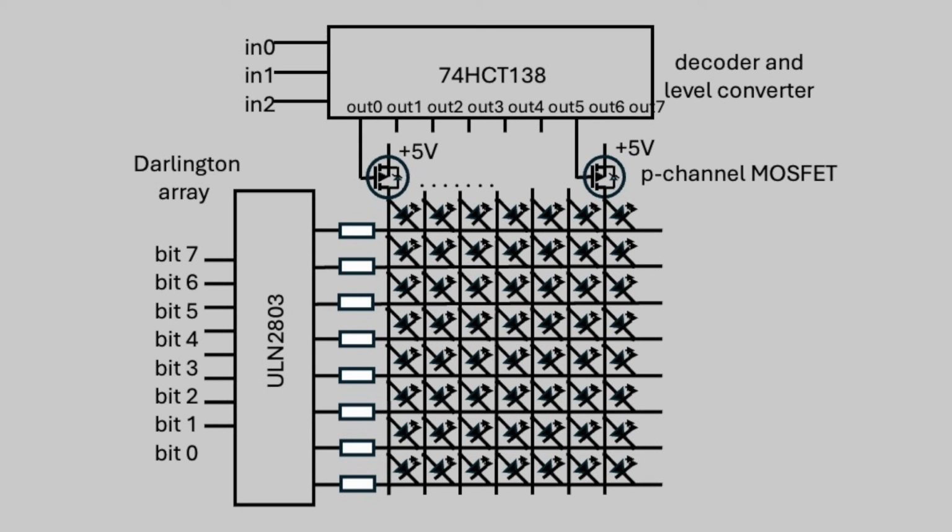In order to achieve sufficient brightness of the LEDs, they are operated with a high peak current of up to 60 milliamps. This results in short, strong current peaks that need to be controlled and regulated accordingly. The rows of the matrix are connected to ground using a Darlington transistor array when an LED is to be switched on. The use of Darlington transistors relieves the outputs of the microcontroller and makes the current peaks fast.